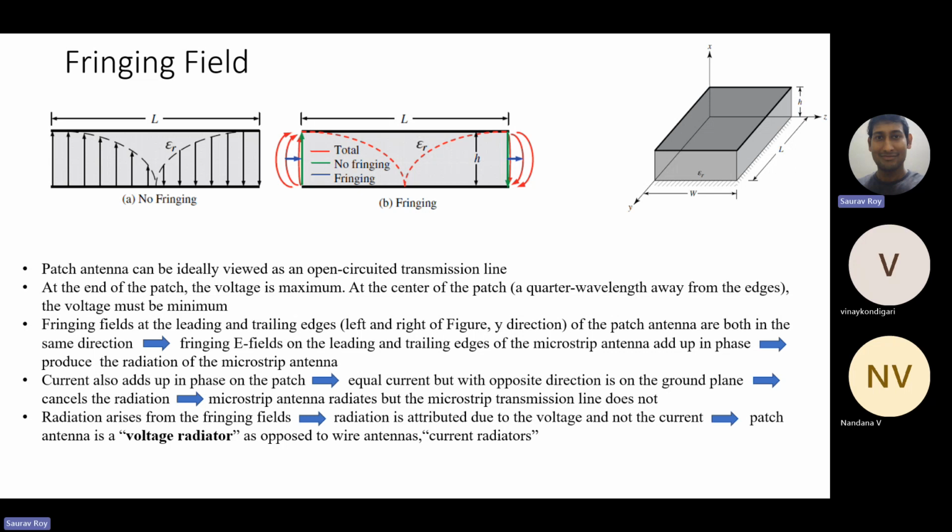So that's why you see that the electric field also, in the left side picture, shows the electric field configuration. At the right side it is maximum, as well as the left side. In between it becomes 0. If you remember, the length L is lambda by 2. Okay. So in lambda by 2, what happens? The field goes through one half wavelength variation.